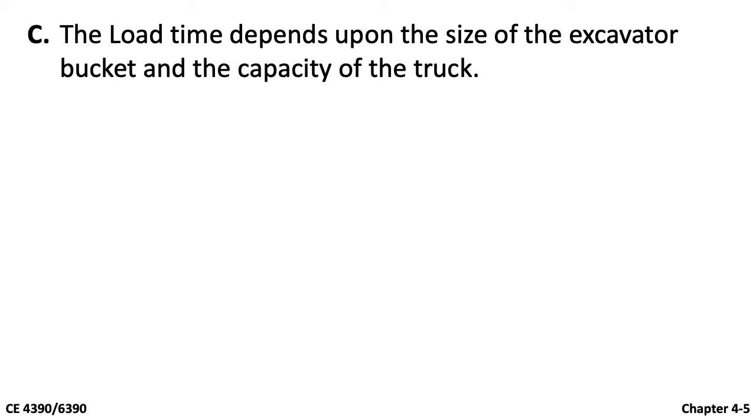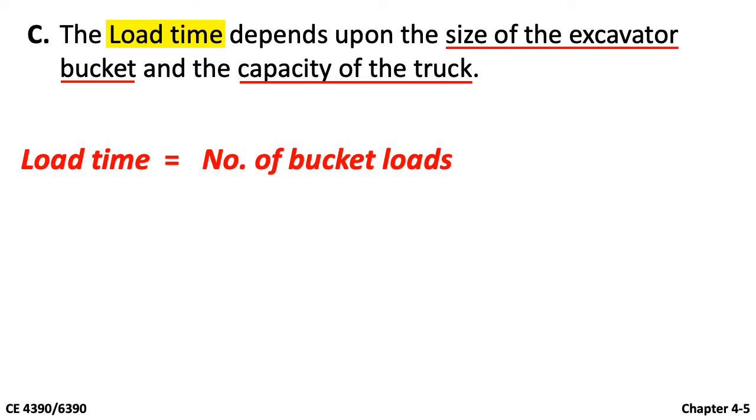Okay, load time depends on the size of the excavator bucket and the capacity of the truck. A small excavator needs more time, and loading takes more time if you're using trucks with a larger capacity. To calculate load time, you multiply the number of bucket loads by the cycle time of the excavator. Here, the number of bucket loads refers to how many cycles the loader must perform until the truck is full.